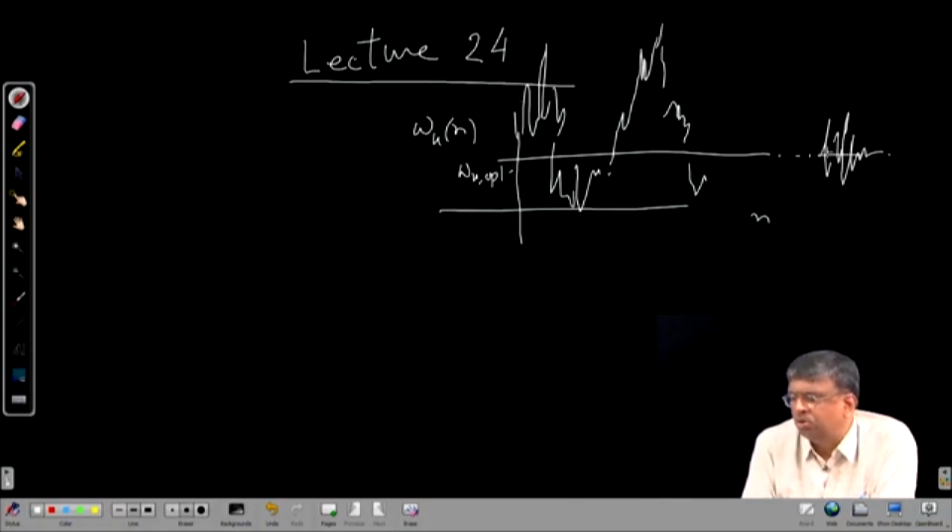So, it can indicate that on the average the value is small, and we are happy, but actually not, because plus and minus both are there, so they cancel each other. But the moment you take variance, it is the difference between w_k(n) and w_k opt, and you take the square of that increment. So positive or negative increments both give positive power, and you take their average. If that is less, then the range of fluctuation will be less.